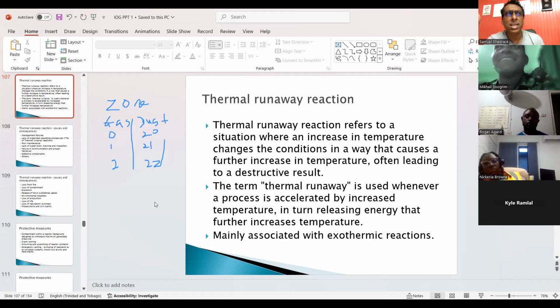If I'm trying to think of some simple examples, it's like if you're heating a vessel, maybe a pot on your stove, and it starts to overflow. The overflow will continue because it got enough heat already. Even if you turn off your burner, there'll be a certain degree of overflow. That's why it's called a runaway reaction: if you stop the energy supply, it's still going.